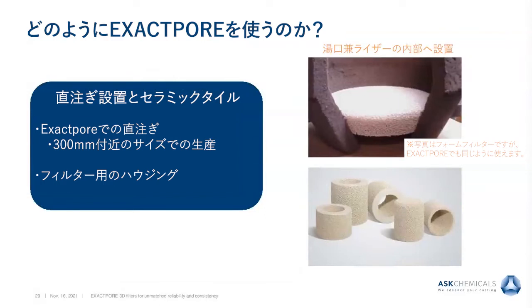This tapered filter is placed in a neck down riser where the metal will be poured into the filter, allowing the oxides to be removed and the modification of the metal into the casting cavity. Once full, the filter will be allowed to float, and that will maximize the cross-sectional area of the riser with the casting and provide efficient feeding.